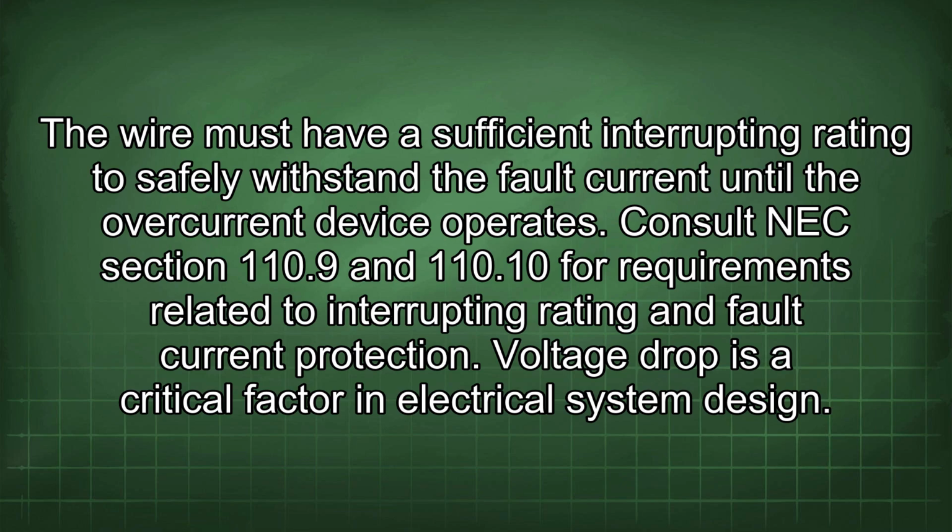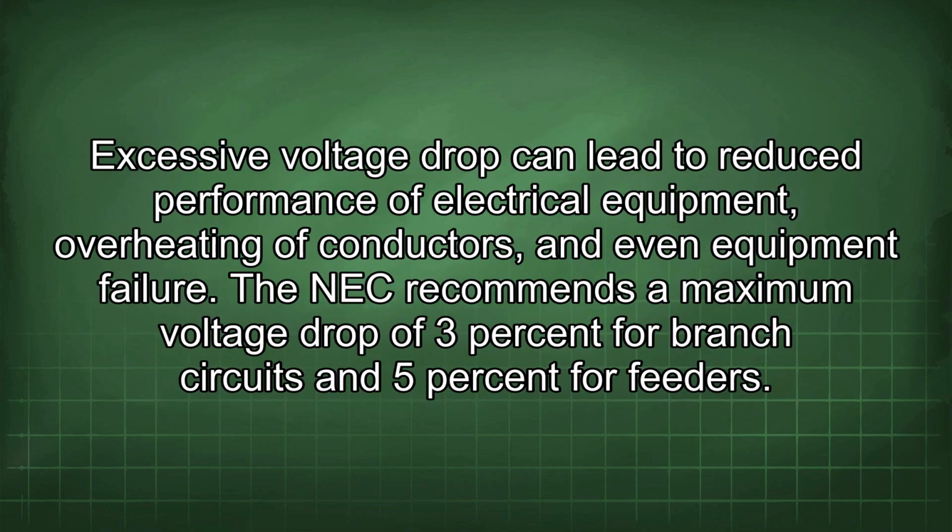Voltage drop is a critical factor in electrical system design. Excessive voltage drop can lead to reduced performance of electrical equipment, overheating of conductors, and even equipment failure. The NEC recommends a maximum voltage drop of 3% for branch circuits and 5% for feeders.